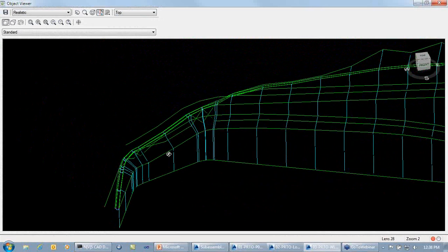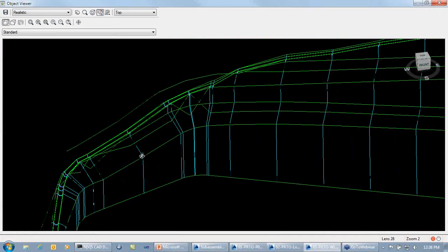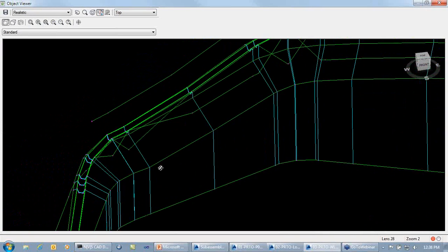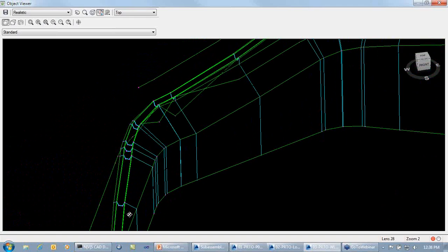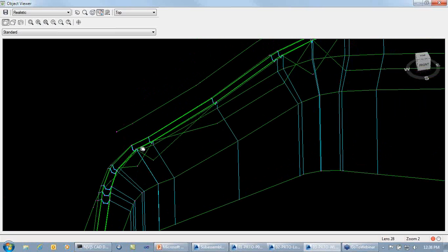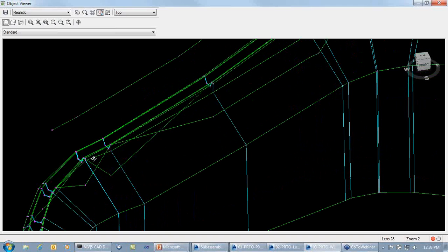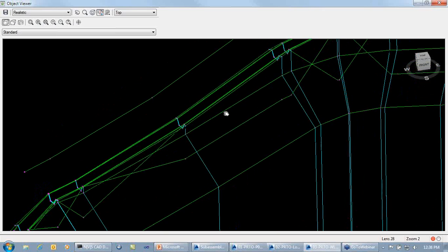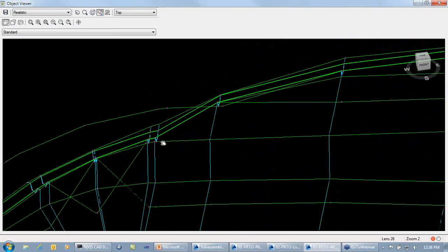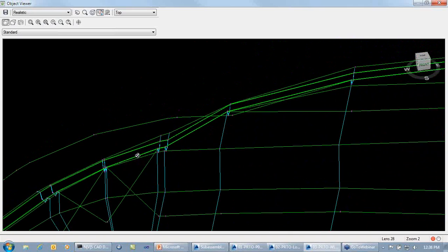I have it doing some odd point codes being linked here, so I apologize for that. But what we'll see now, the conditional will work, so we'll see as we go along the top of the first wall, as long as that sample depth is less than 5, it's putting in just a link and then the ditch. Okay. As we come around, we get to these sections here where our cut value now is greater than 5, so we can see we're now getting the vertical link representing the second wall, and it gets a little taller as we come along, and that is now targeting that profile, and then that is going straight back.